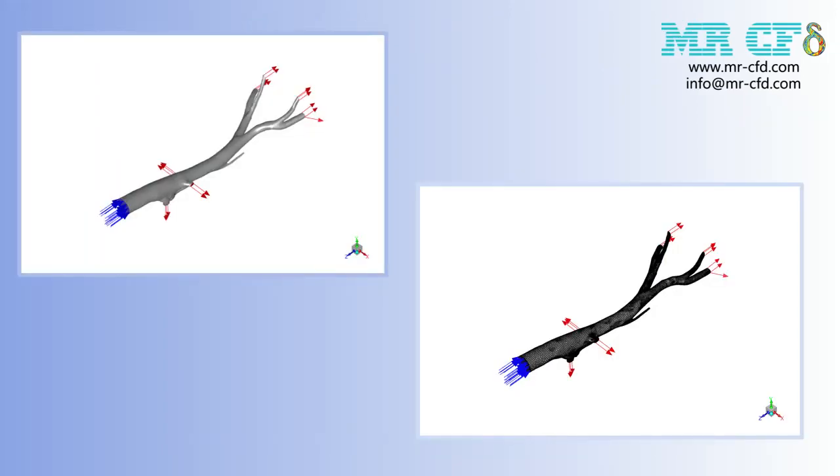The geometry of the present project should be repaired before generating the mesh. Some powerful tools can assist us in fixing the geometry, such as SpaceClaim, ICEM, and DesignModeler. In this study, we used ICEM to fix the geometry and to generate the mesh.